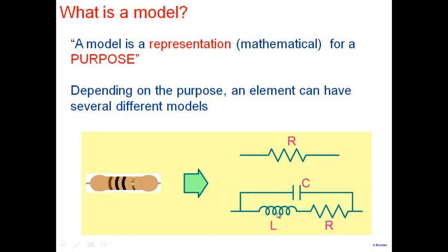Now, why am I building this? Well, every lead that is there, every wire actually has an inductance. You can calculate the inductance. Okay, so every wire has an inductance, so I put an inductance here. And between two leads here, between here and here, there's always a capacitance. Because note that if I have, let's say, 1 volt here and 0 volt here, and through the air, I have a fringe capacitance. So I always have a capacitance.